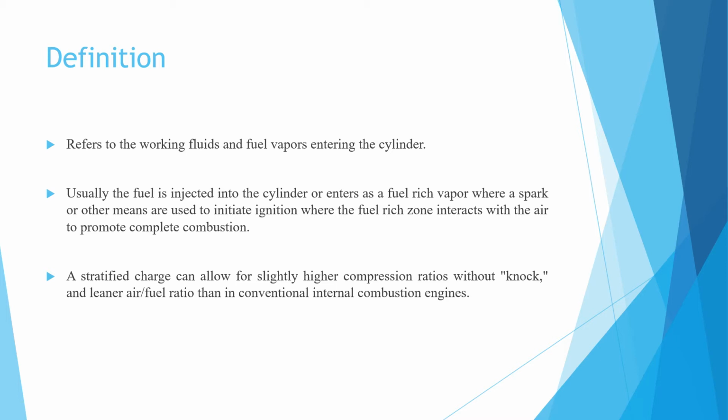A stratified charge can allow for slightly higher compression ratio without knock and lean air fuel ratio than a conventional internal combustion engine.